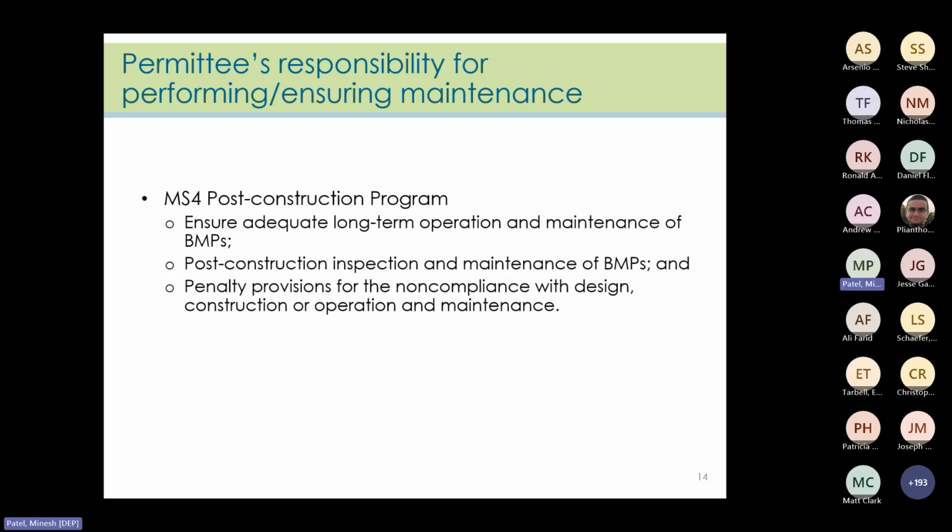Under the Municipal Post-Construction Stormwater Management Program, you can start with an inspection program that includes notification of the responsible parties. A municipality can opt to enact penalty provisions into its ordinances as a step towards enforcing compliance, or they can even create a licensing program to offset inspection costs.